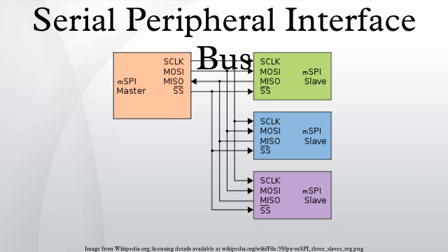Other programmable features include SPI chip selects and transfer length delay. SPI controllers from different vendors support different feature sets. Such DMA queues are not uncommon, although they may be associated with separate DMA engines rather than the SPI controller itself, such as used by multi-channel buffered serial port. Most SPI master controllers integrate support for up to 4 chip selects, although some require chip selects to be managed separately through GPIO lines.